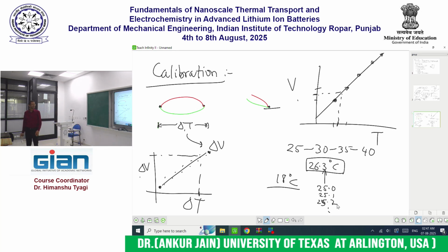Sometimes we do it the right way and sometimes we are in a hurry. The experimentalist will always make many compromises to calibrate. But calibration is a holy thing. You cannot proceed forward without a good calibration. With a large temperature range that we are... Yeah, exactly. If you're doing measurements at high temperatures, from room temperature to 500 degrees C, you cannot calibrate with plus minus 0.1, right?